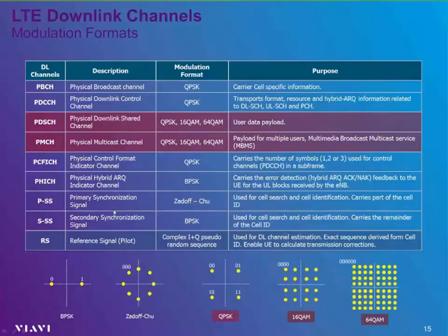Now, the primary synchronization signal and secondary synchronization signal, these two can be a little confusing, because when I first learned about LTE, I came to realize that between the primary and secondary synchronization signals is how the sectors are otherwise identified. They're called PCIs. PCIs can have up to 504 different values. You use all of them, unlike CDMA 2000 EVDO, where you have a PN increment and you only use a fraction of the total available. In LTE, you can use all of them.